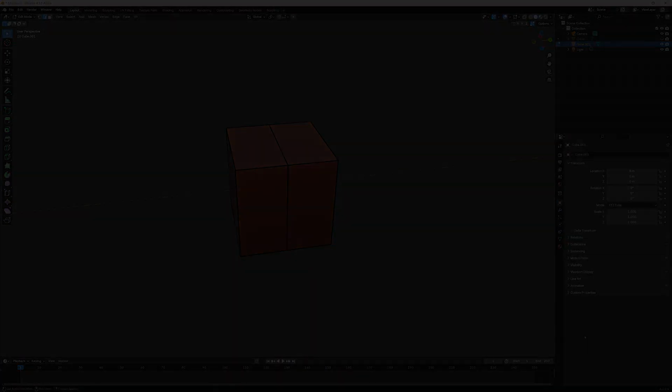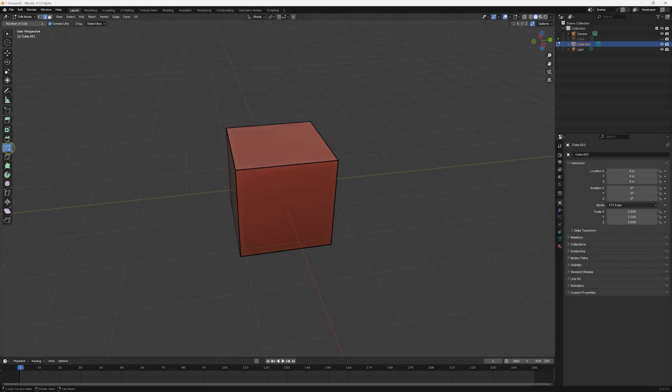the process. Once the Loop Cut tool is selected, when we move the mouse pointer over any face, Blender displays a yellow line loop showing where the new edges will be placed. If we place the pointer near the top or bottom of the face, we'll see a vertical loop, and if we place the pointer to the right or left, we'll see a horizontal loop. Notice that we don't need to select any elements in the mesh before executing this option. By default, the new edges will be placed at the center of the existing edges to be cut through. All we need to do is left-click the mouse.